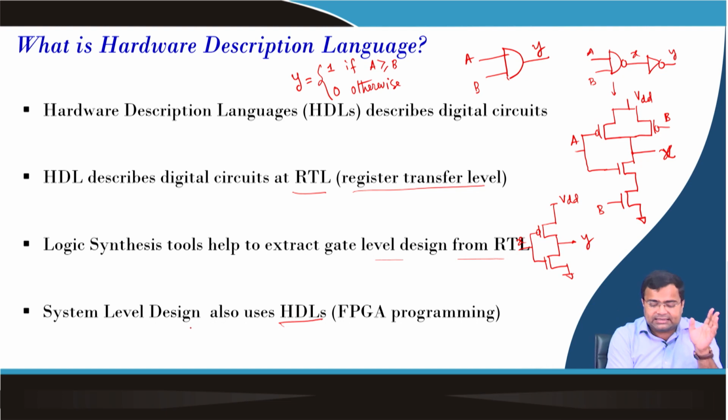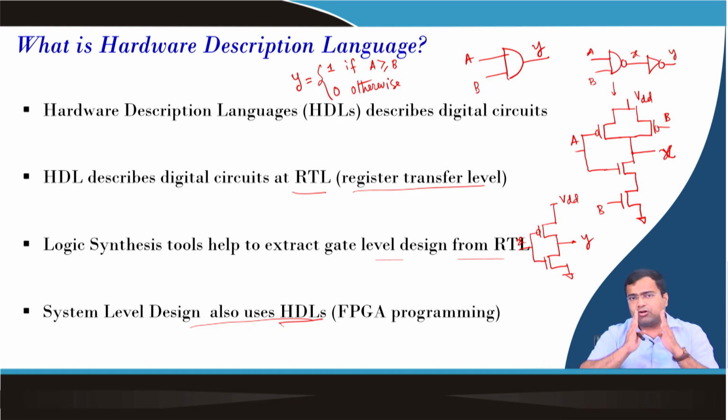So HDL has benefits: you can visualize your design at the circuit level or at least the logic gate level, you can optimize the timing diagram very precisely, and you can also prototype using FPGA. But if you go for a microcontroller, you have little flexibility because most of the architectures are already well defined. You do not have much access inside the digital block, rather you will have either a high level language or maybe assembly language, depending upon how the manufacturer provides for coding.